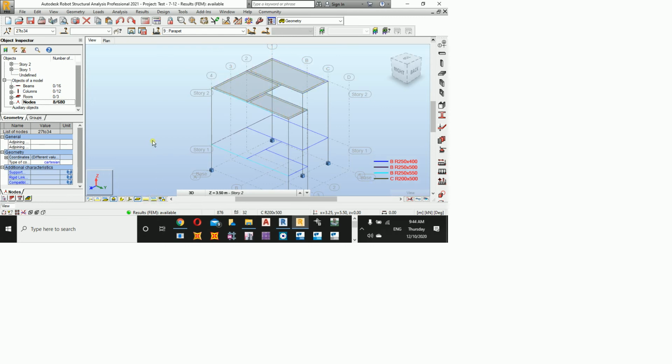Anyhow, for your error, if there is any error coming to any person, you just click on the error and it will show you. Now, if overlapping, it means two beams are entering inside each other or two columns are entering inside each other. Okay, so can you click on the error? Can you click on that later?